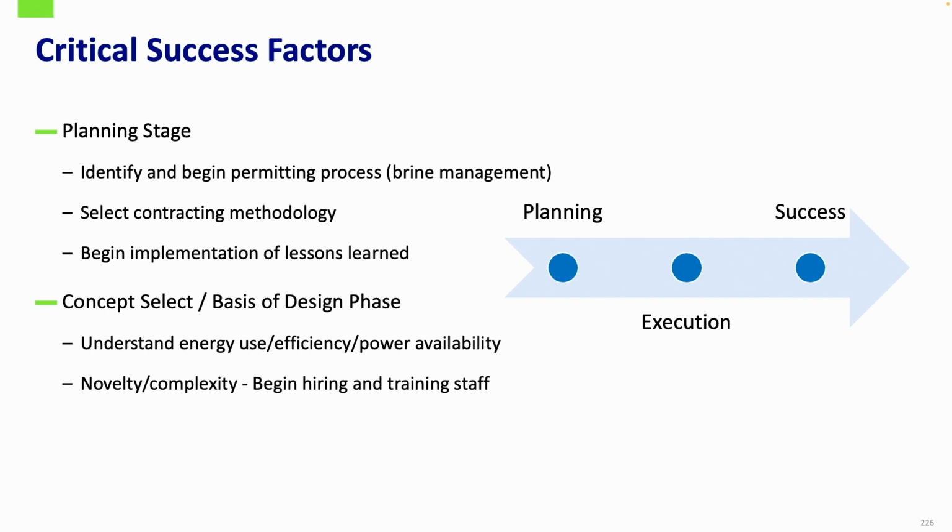And then from the concept select phase, basis of design, understand energy use on the project, because desalination, from a water treatment perspective in the US, uses the most amount of energy. So you have to understand that use, the efficiencies in the treatment process, as well as the power availability in the area. And also in considering the design, the novelty and complexity of the project. Most of the technologies and the unit processes in desalination are new to operators, so you've got to get them involved early in the project.